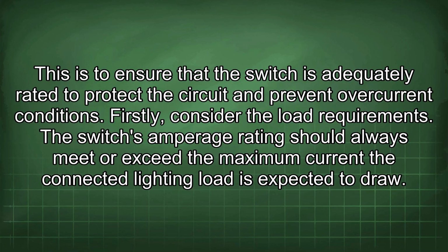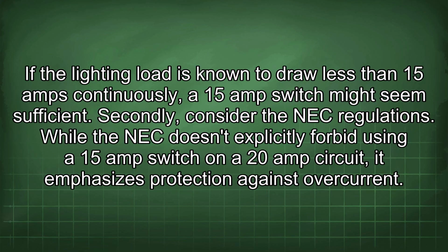Firstly, consider the load requirement. The switch's amperage rating should always meet or exceed the maximum current a connected lighting load is expected to draw. If the lighting load is known to draw less than 15 amps continuously, a 15 amp switch might seem sufficient. Secondly, consider the NEC regulations.